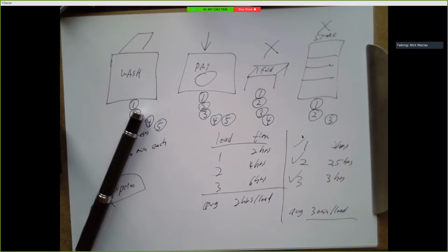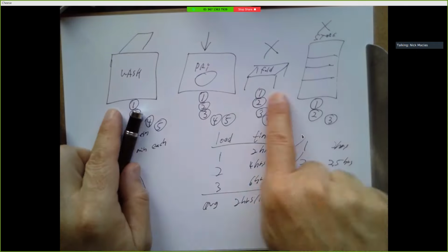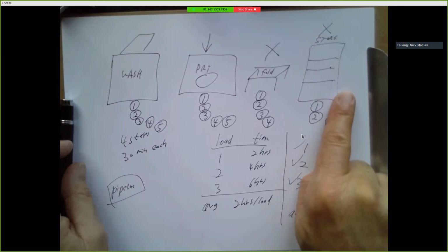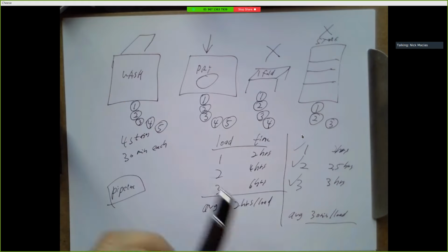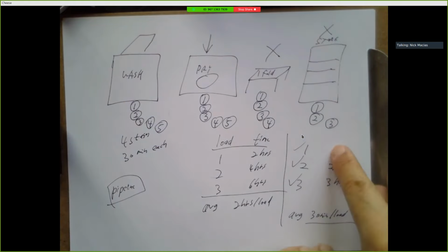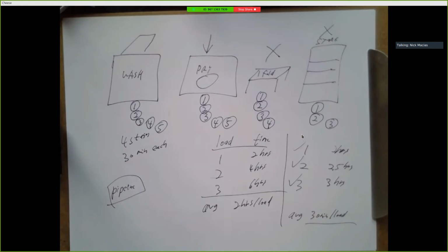Okay, so these are all things that happen inside processors, and they critically affect the design of the processor, the design of the program, the design of the compilers and the assemblers, and everything else. And it's all about trying to have a long pipeline that you can use efficiently and trying to avoid having stalls where you have to change what's going through your pipeline and basically lose your pipelined output.